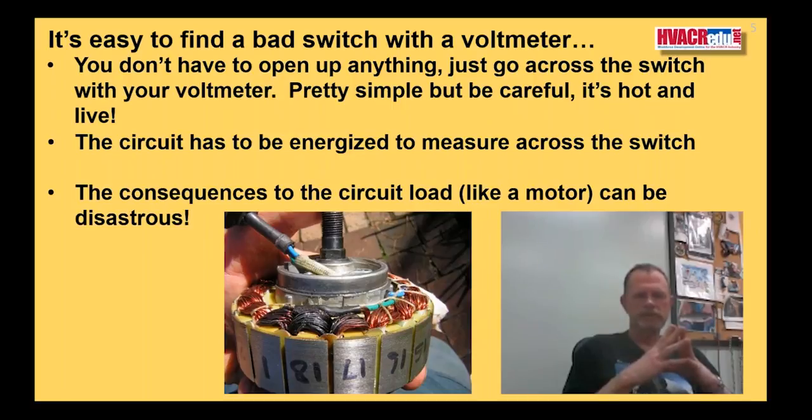Look at all the switches in that circuit, because if you had a bad switch, resistance in the circuit could have easily taken that motor out because it dropped voltage to the motor. What happens when you drop voltage to a motor? Amperage goes up. What happens when amperage goes up? Heat goes up. What happens when heat goes up? You start frying insulation on the motor windings. Bad switches, by the way, are primarily the scourge of inductive loads, i.e. windings, coils, motors, all those types of inductive loads that you would find in an HVAC system.